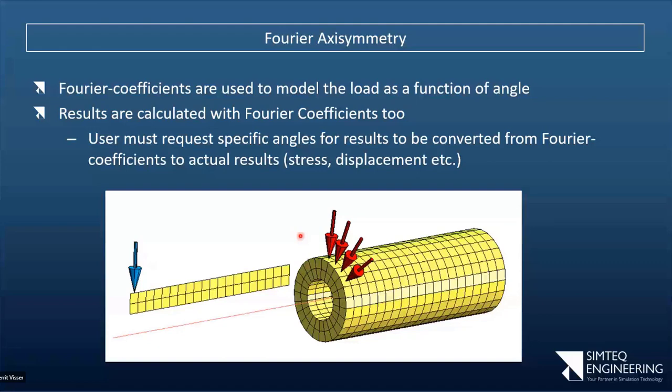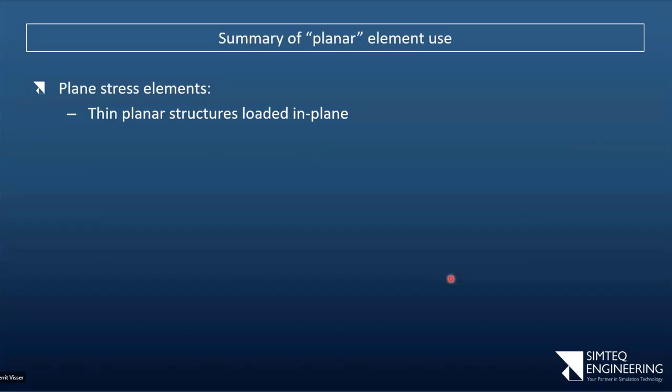So in other words, it's a bit more painful to post-process this, but it's worthwhile in terms of runtime. It means that for this model I can have a lot finer mesh there than I'd use for this one, for the same total number of elements, or I can use a lot fewer elements for the same accuracy of answer. So it's a really convenient way to do things, but again, it's very limited in its applicability.